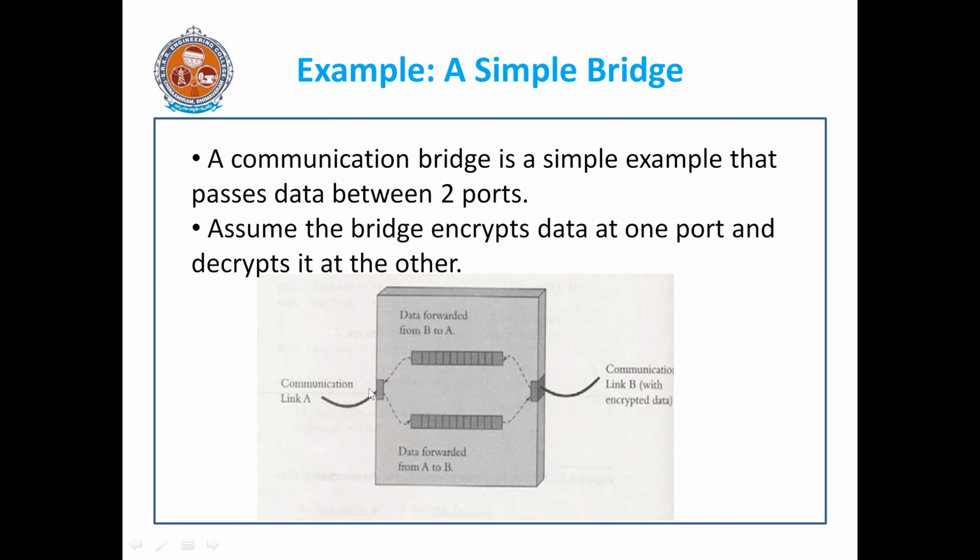Also here you should have the encryption and decryption. Suppose you receive a character here, you should write the encryption routine, and also here you have to write the decryption routine. So the encryption and decryption routines are also compulsory. Transmitting and receiving the characters are given as interrupt service routines. Shared data sections are made here, and you should also take care of the shared data.